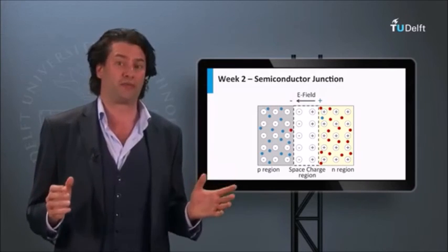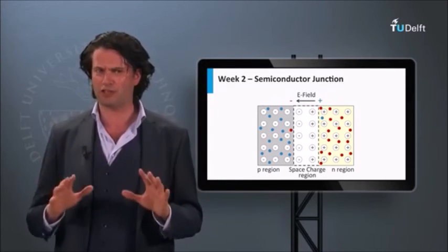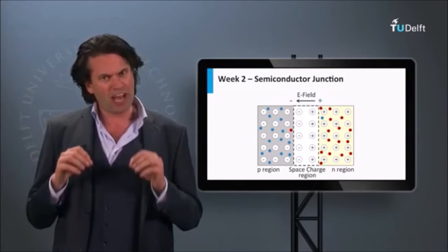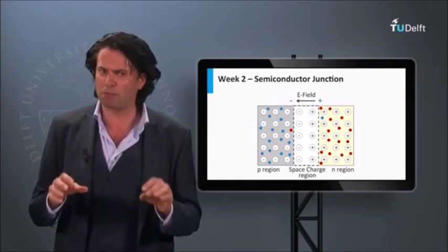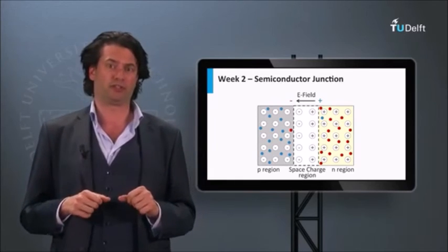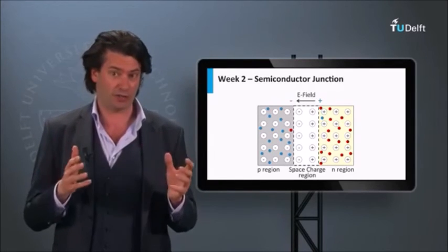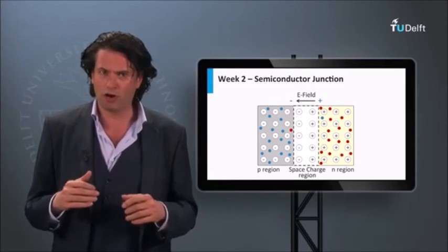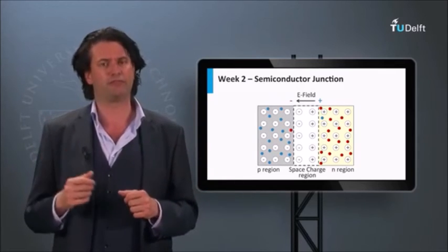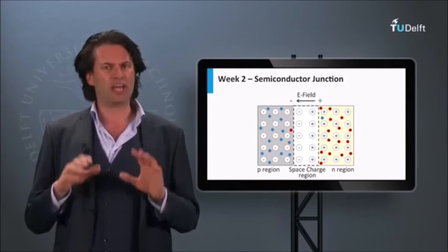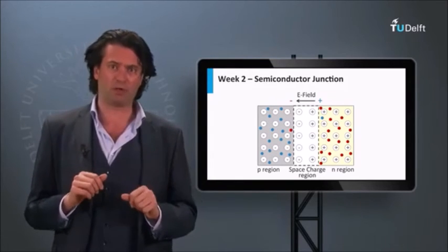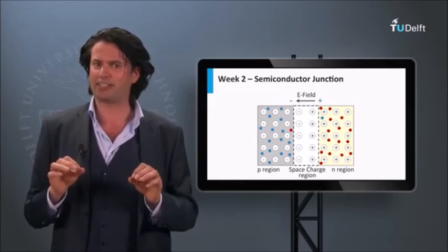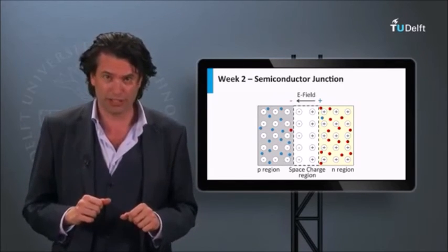In weeks 2 and 3, we have discussed the physical fundamentals of photovoltaic technology. We have discussed various properties of semiconductor materials, such as the valence and conduction band, its band gap, and the transport mechanism of the charge carriers, like drift and diffusion. We have discussed the working principle of PN junctions. These junctions separate the light-excited minority charge carriers.